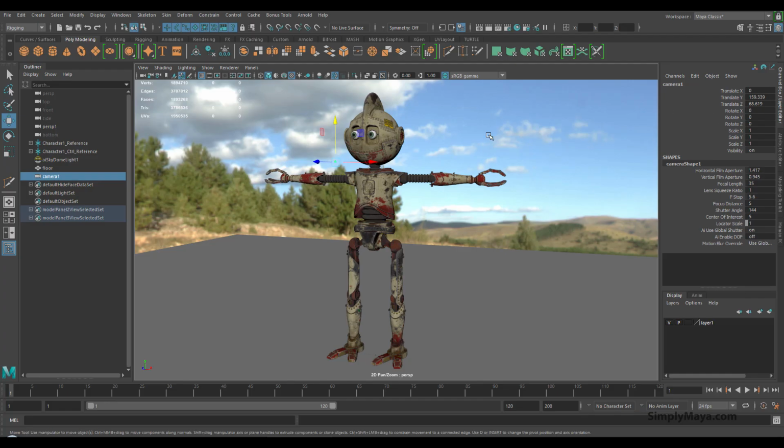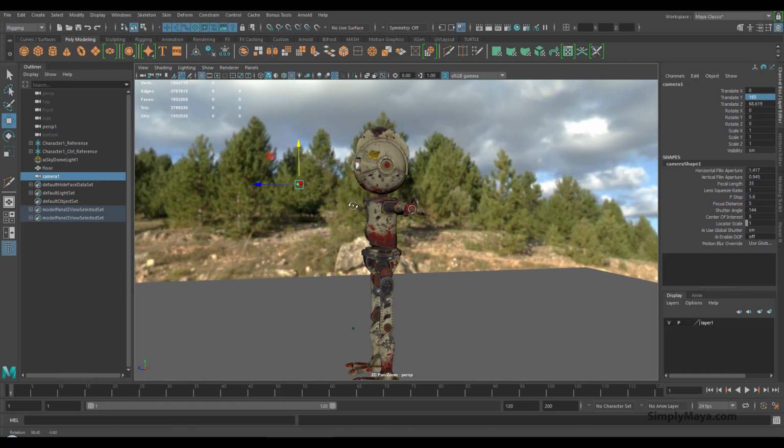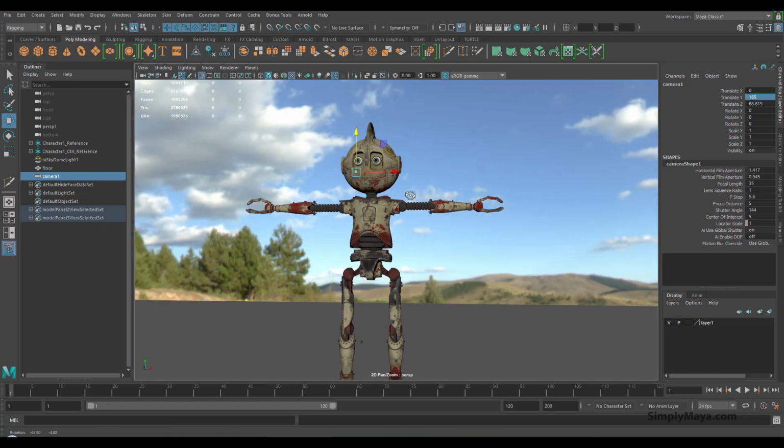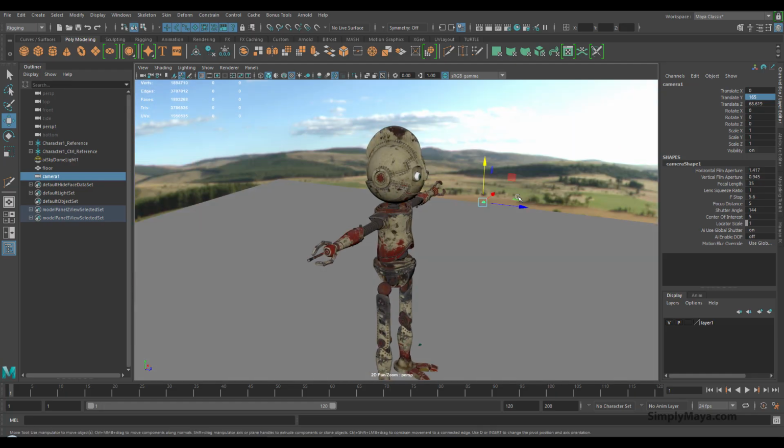Like, I know how tall I am. I'm around 6 feet, so about 183 centimeters, I think that works out at. So my eye level height is probably around 165 centimeters. So the first setting I could set on the camera, don't know why that's set to 400, I'm not that tall, is 165 centimeters. And that brings us almost eye line with a robot who's a little taller than me, I believe. So that would be about right.